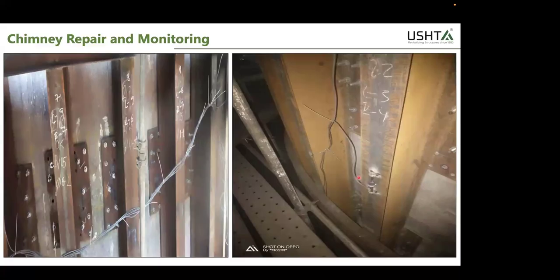I mean, we'll have that work completed. So what we did there was, we are building a small standby steel chimney there, diverting the flue through that temporarily, and we'll remove the entire lining from inside, do jacketing from inside, and do lining inside, and in the cavity of the lining, we'll do additional jacketing. So we'll strengthen the chimney also.